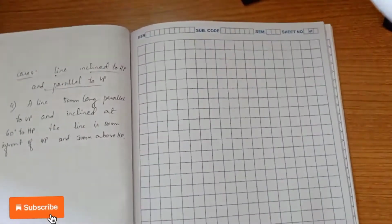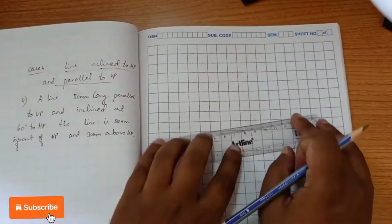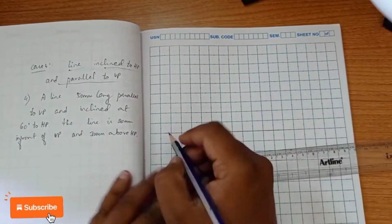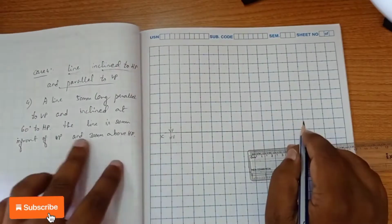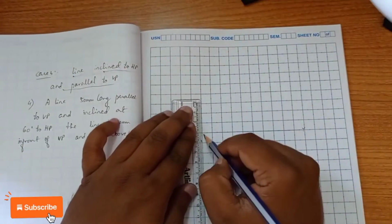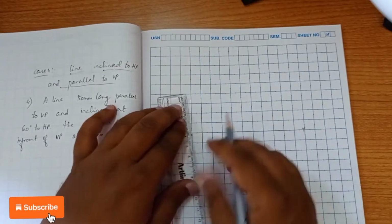For that, first I am going to draw an XY line and the first quadrant. VP, HP, Y. You can see here the end of the line is 20 mm in front of VP, 30 mm above HP. So 30 mm above HP means this is 30 and this is 20.